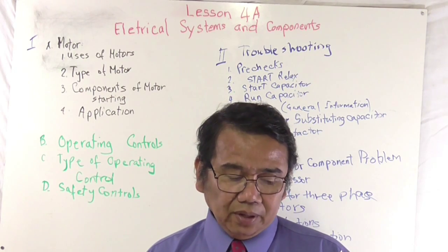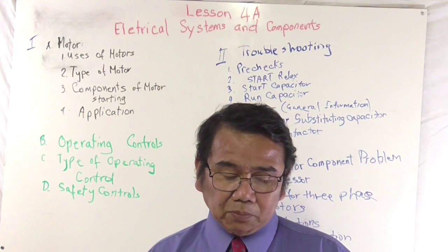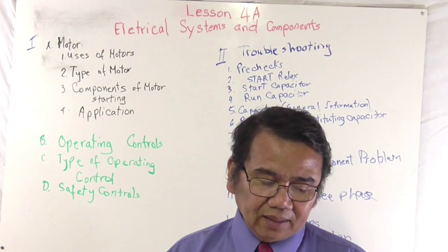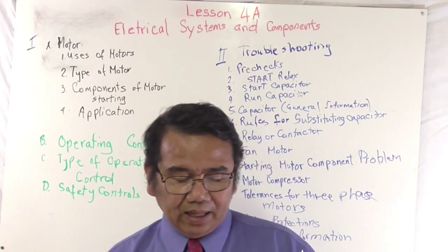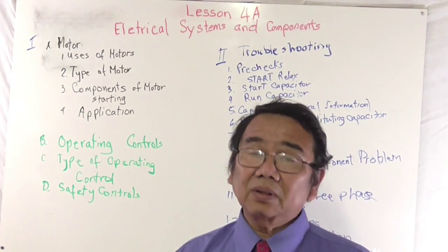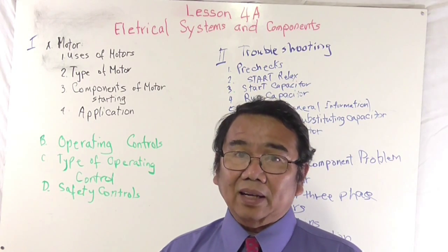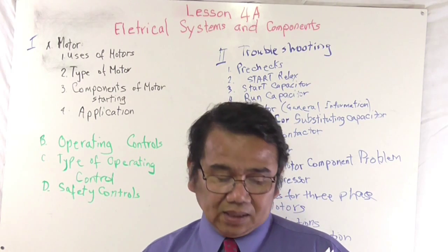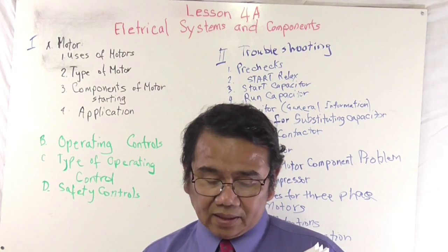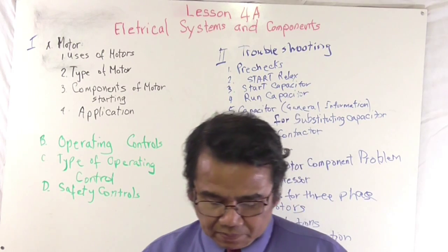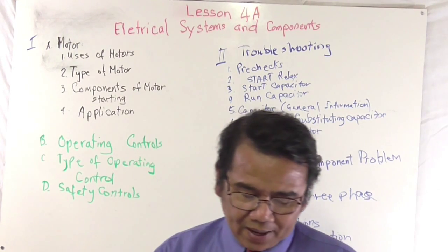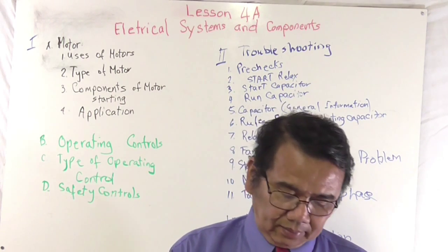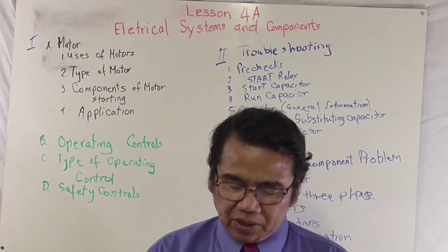capacitor stays in. Then you have improper wiring, improper size potential start relay, voltage is low, run capacitor bad, start relay is bad, high head pressure, and then you got your compressor mechanical drags. Mechanical drags means something is rubbing. It starts and runs, and it cycles on overload. You got improper voltage, run capacitor bad, high or low voltage, compressor mechanical drag, and then improper size potential start relay.